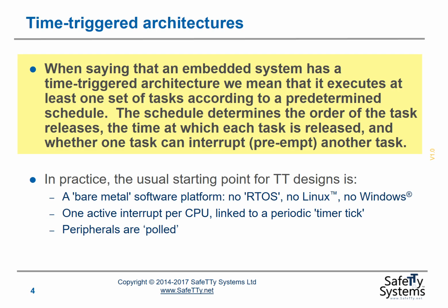So when we say that an embedded system has a time-triggered architecture, we mean that it executes at least one set of tasks according to a predetermined schedule. The schedule determines the order of the task releases, the time at which each task is released, and whether one task can interrupt or preempt another task. In practice, the usual starting point for TT designs is a bare metal software platform, no RTOS, no Linux, no Windows. We have one active interrupt per CPU linked to a periodic timer tick. All peripherals are polled.